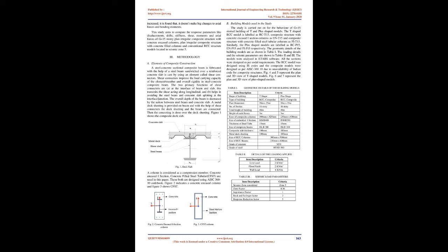Sohail Sheikh [3] conducted a study on the behavior of concrete encased columns in irregular buildings under seismic conditions. A detailed analysis of a multi-storey G+20 building having various irregularities with concrete encased columns has been carried out against RCC columns in mass and stiffness irregularity. Base shear was found to be reduced in concrete encased columns in both the irregularities. The time periods and the displacements were found to be higher in the composite structure when compared with the RCC structure. He concluded that concrete encased columns are suitable for stiffness irregularity buildings due to their high stiffness property, which enables the structure to resist.